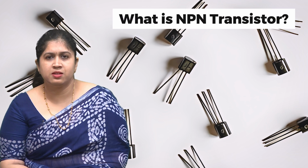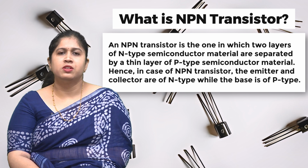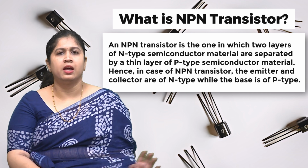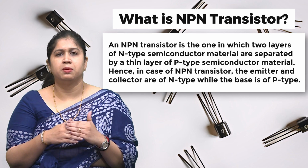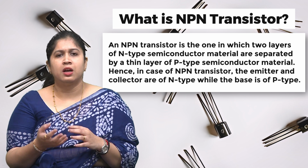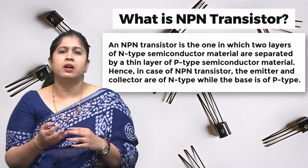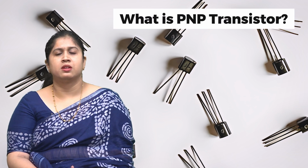Now we discuss the NPN transistor. An NPN transistor is one in which two layers of N type semiconductor material are separated by a thin layer of P type semiconductor material. Hence, in case of an NPN transistor, the emitter and collector are of N type while the base is of P type. Now we discuss the PNP transistor.